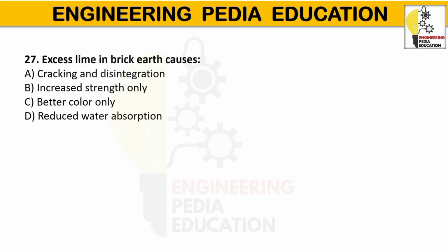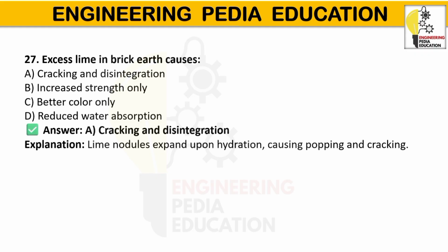Excess lime in brick earth causes: increase strength only, better color only, reduce water absorption, or cracking and disintegration. So the correct answer is cracking and disintegration. Lime nodules expand upon hydration, causing popping and cracking. Excess lime in brick causes cracking and disintegration.